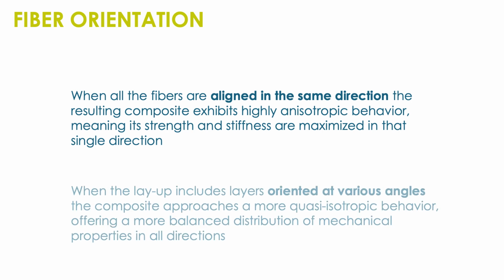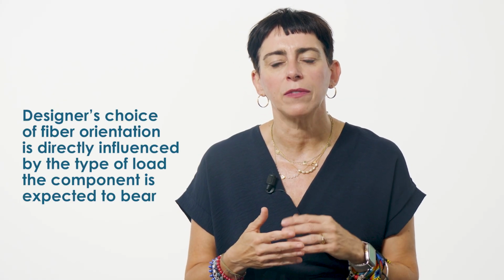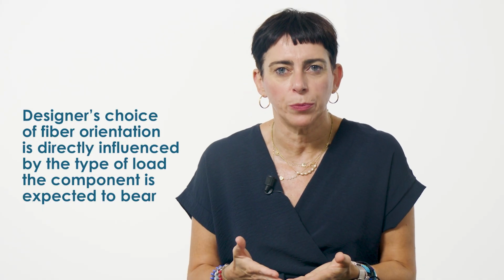On the other end, when the layup includes layers oriented at various angles such as 0, plus minus 45, plus minus 90, the composite approaches a more quasi-isotropic behavior, offering a more balanced distribution of mechanical properties in all directions. The designer's choice of fiber orientation is directly influenced by the type of load the component is expected to bear.